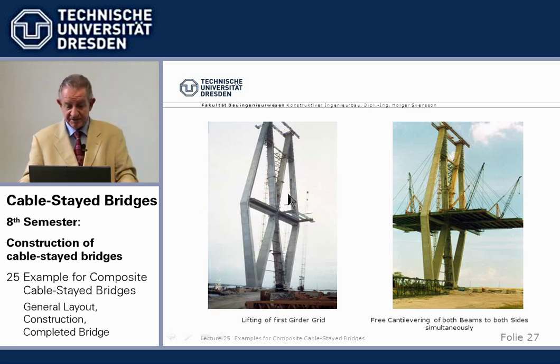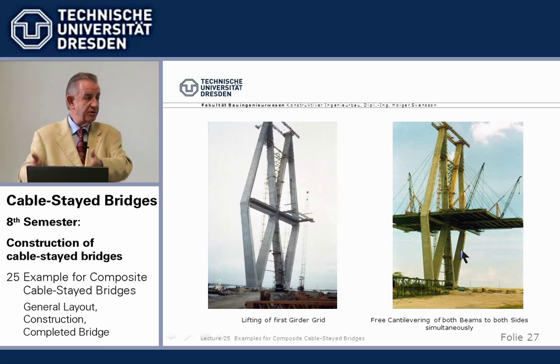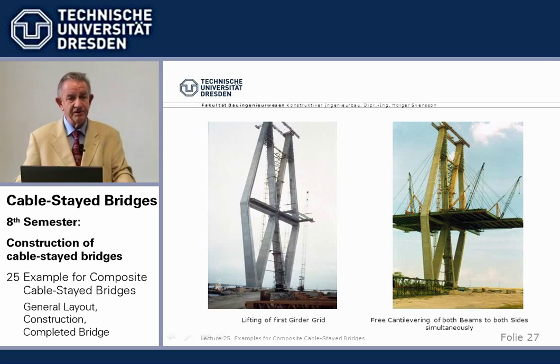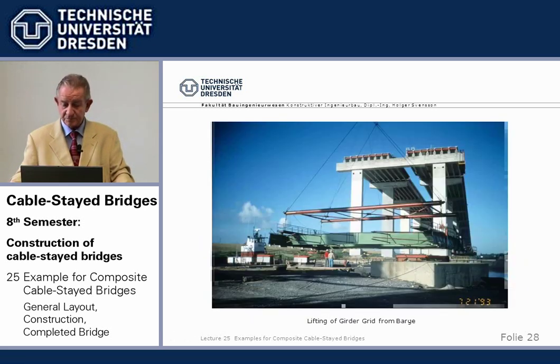It started just with the tower crane lifting up the first piece of beam. After that, lifting derricks were installed on the beam. We used these derricks for lifting all the material which came by water and lifted up. You know, we could also transport it on the beam. We could use floating cranes. This was the decision the contractor made.